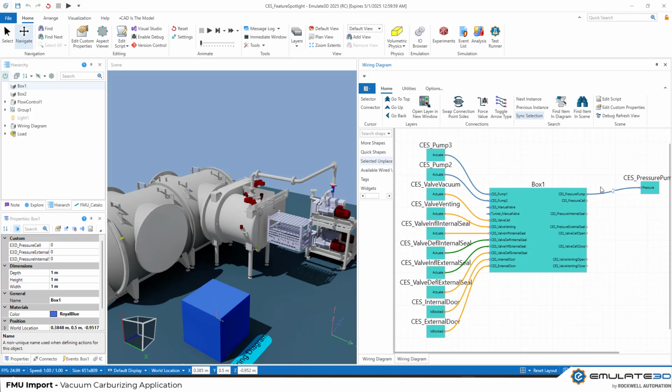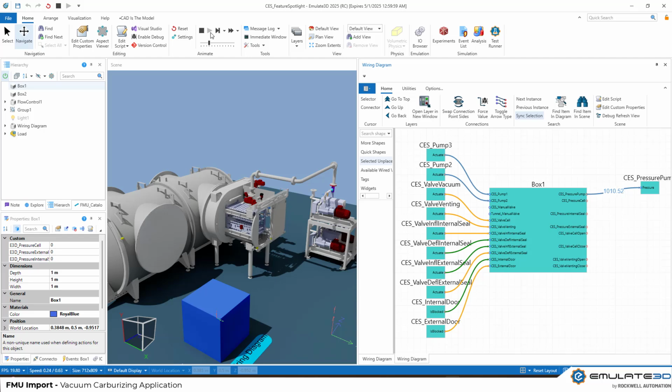You will be able to see when inputs are actuated based on the color of the wire, and you'll be able to see the pressure of the system change with the pressure pump property. The target for this system is less than 4 millibar of pressure. First, we'll add the metal to this chamber, where we'll be able to use a pump to reduce the pressure. For demonstration purposes, I've made the exterior invisible. Notice that as we've modeled this with high-fidelity physics, the gas pressure decreases non-linearly. When the pressure has reached 4 millibar or below, we'll be able to release the metal into the larger system.